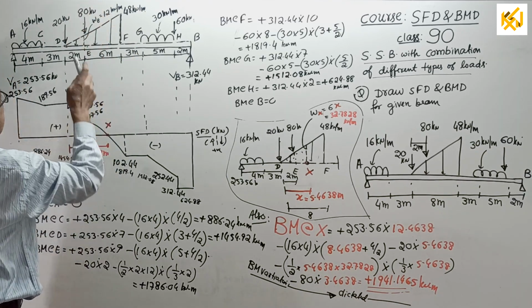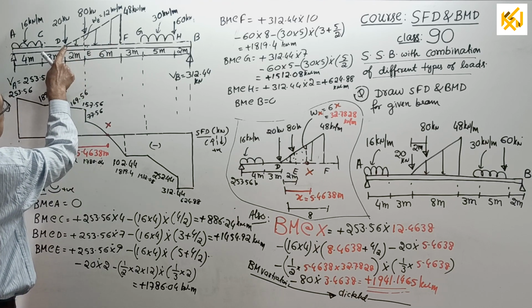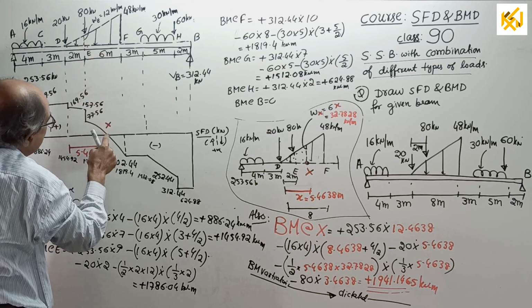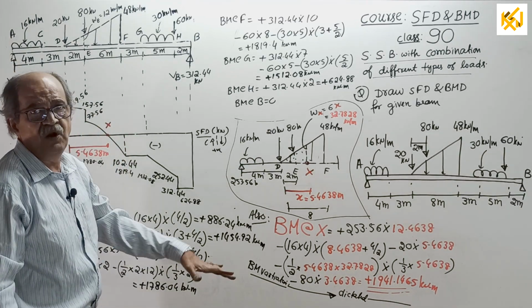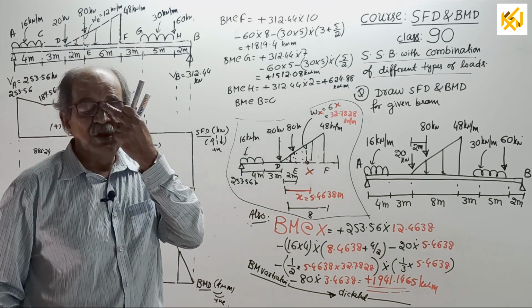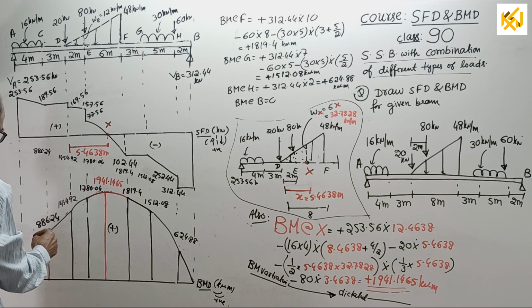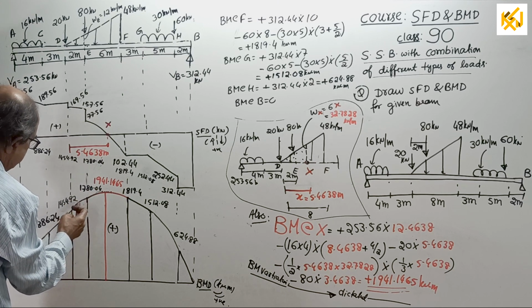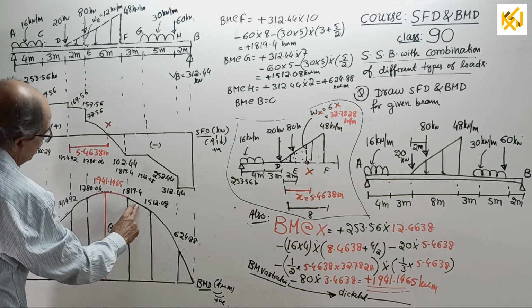And one thing I forgot now, the shear force diagram. When you start from here, 0 intensity here, 0 slope here, slope increases, again slope increases here, here maximum slope. This I explained earlier. So now I will draw the bending moment diagram and close the class. The diagram is drawn here. Parabola second degree, linear. From here to here is parabola of third degree. This is also third degree. They are different curves. And this is linear.